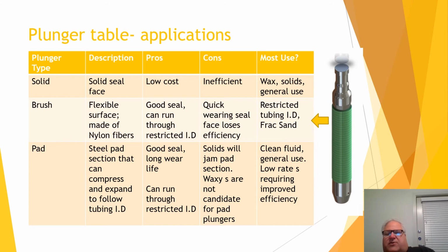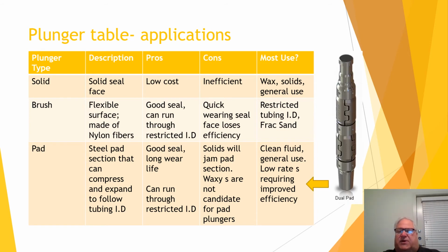So they do have a great application, but I typically look to use them in lower rate wells, lower GLR wells. They have to be clean, and you would never use them with wax or solids. If you've got a nice clean well that's making a nice clean oil or a nice clean water, it's a great solution. If you have a really strong well, though, there's probably not a lot of advantage putting these more expensive plungers into the well.